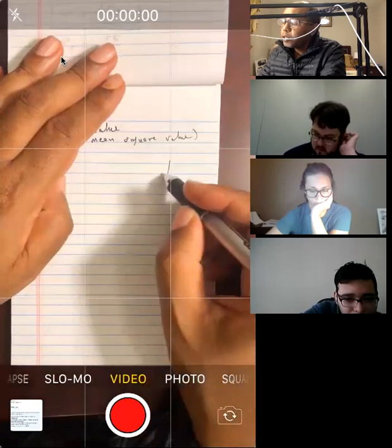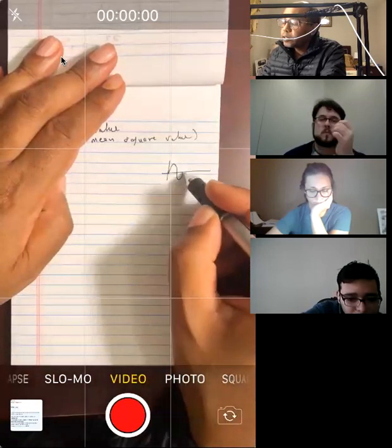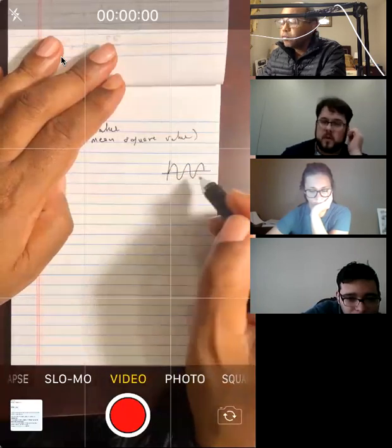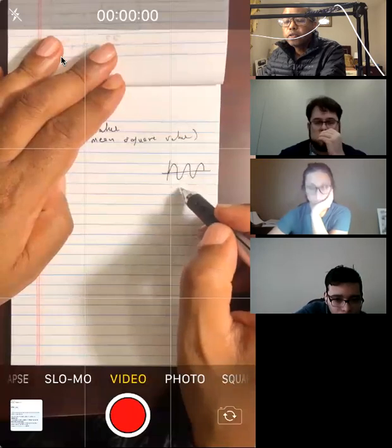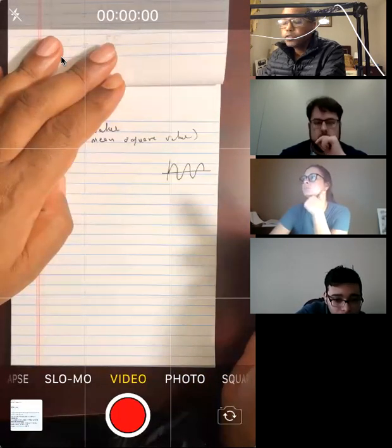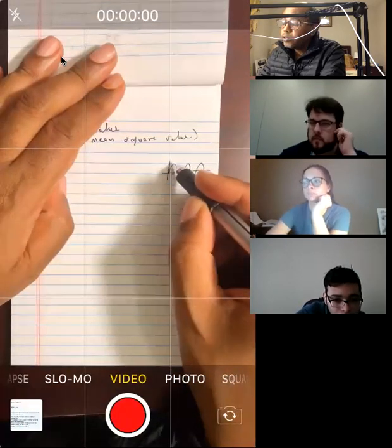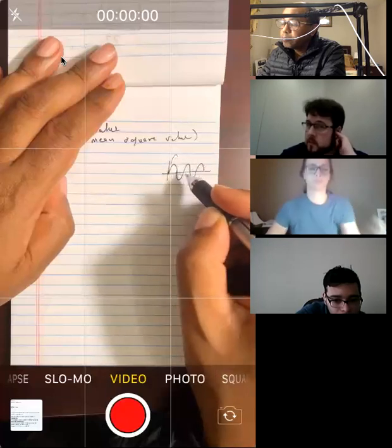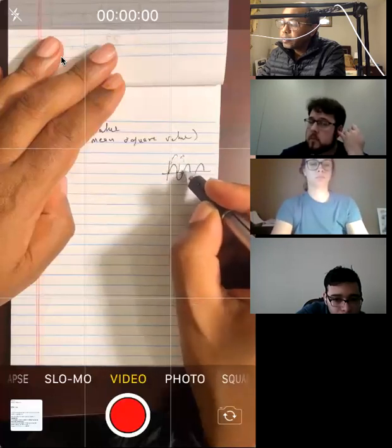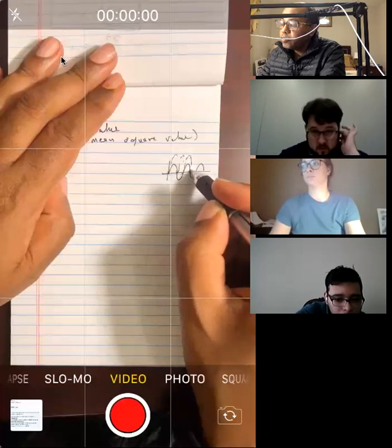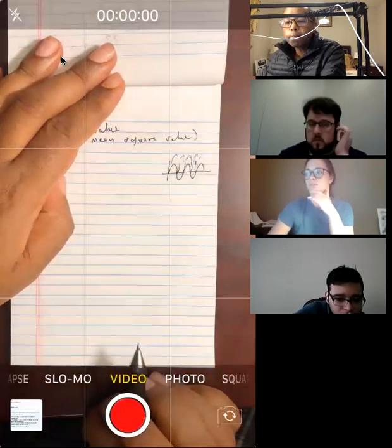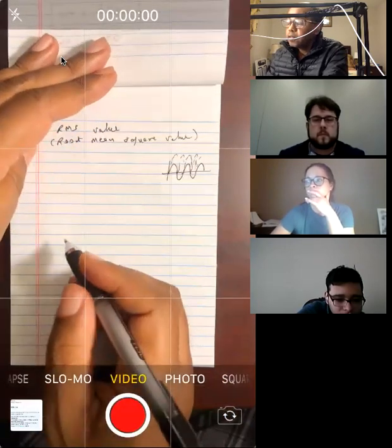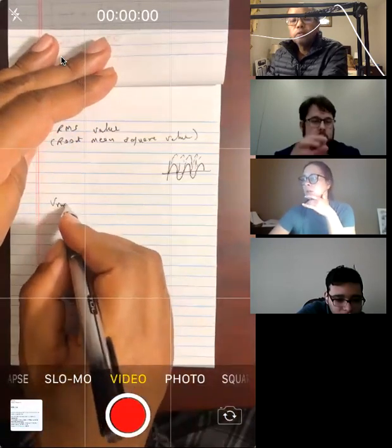But what do you get if you take the average of the signal? What's the average of a sine? Zero, because of the alternation between positive and negative, right? So we have to deal with a different kind of average. What they do is they square this signal, okay? So they get something like this. And then they take the average of that, which is non-zero, and then take the square root, okay? So this is the definition of RMS value.